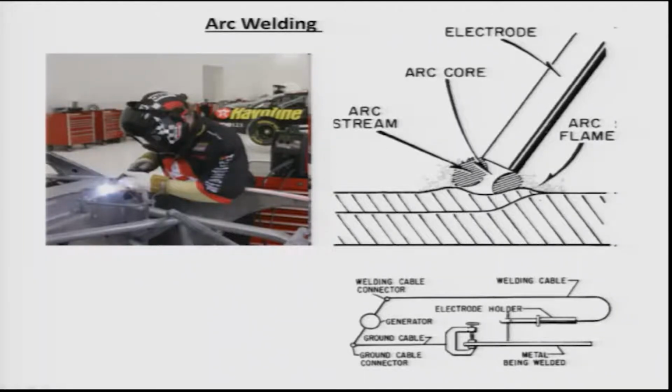Here you see two pieces of metal getting joined together using an arc flame. In this situation only a small amount of liquid is generated between the two pieces of metal, and because the liquid is in contact with the two pieces, there is an enormous number of heterogeneous nucleation sites present on both surfaces. So solidification starts with the heterogeneous nucleation of these grains.